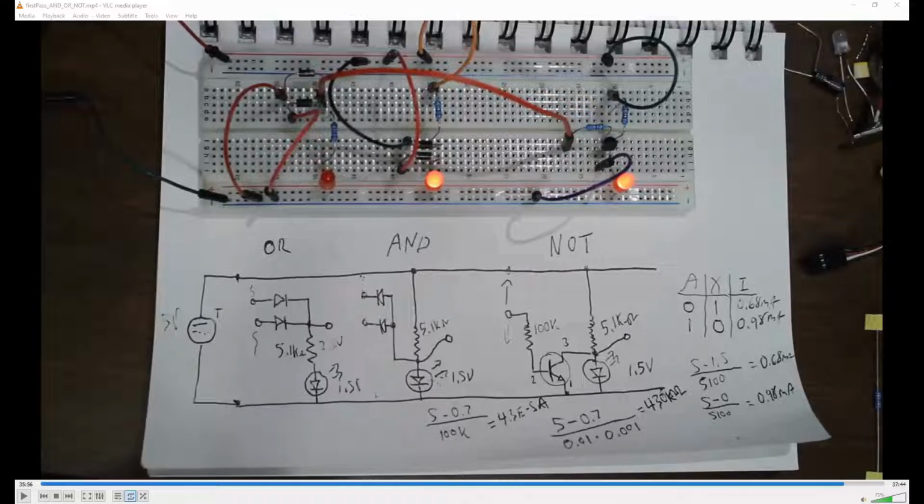I believe the low is low enough to pretty much register as a low on any input, but the 1.5 volts may not be high enough to be at the minimum for the digital inputs of something like an Arduino or a Raspberry Pi to actually recognize it as an active high. Very often you want at least 2.5 volts in a 5 volt system to be definitely considered a logic high at the input.